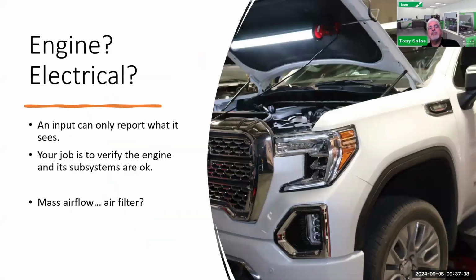So before we start analyzing even PIDs, please note that a PID is only as good as what it's reporting to. In other words, mass airflow sensor. Can a mass airflow sensor be incorrect? DPF loaded, can that cause an incorrect mass airflow reading due to the fact that it's backlogging, it's restricting the flow, and that could cause a mass airflow reading to read incorrect.